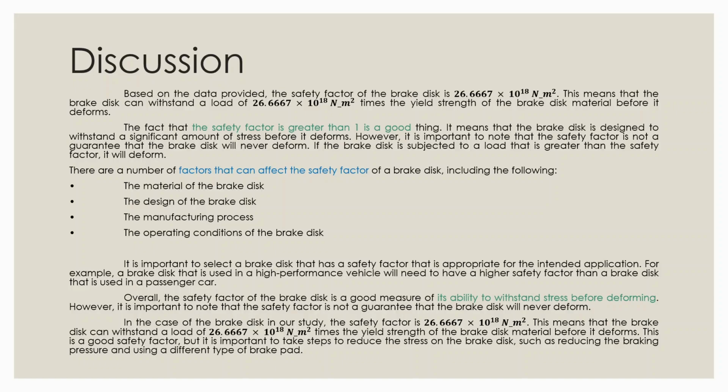This means that the brake disc can withstand a load of 26.6667 times the yield strength of the brake disc material before it deforms. This is a good safety factor, but it is important to take steps to reduce the stress on the brake disc, such as reducing the brake pressure and using a different type of brake pad.